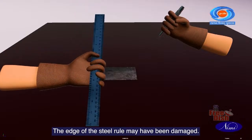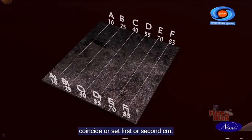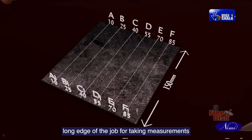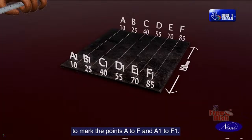The edge of the steel rule may have been damaged. To avoid wrong measurement, coincide or set the first or second cm graduation mark of the steel rule against the 150 long edge of the job for taking measurements and marking of points A to F and A1 to F1. Ensure there is no parallax error while using the scale to mark the points A to F and A1 to